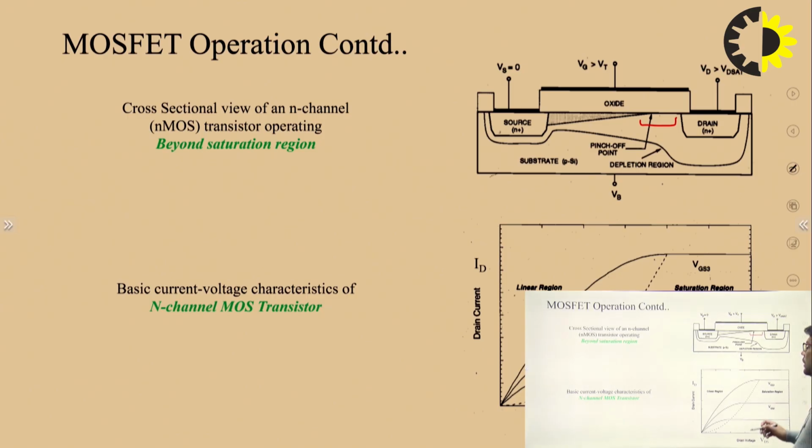So this is the voltage current IV characteristics for the MOSFET. You can see this is a linear region. At a certain voltage we have the saturation region. This is the saturation region, and the locus of the pinch off voltage is always parabolic by nature. So this is the locus of the pinch off voltage, right.